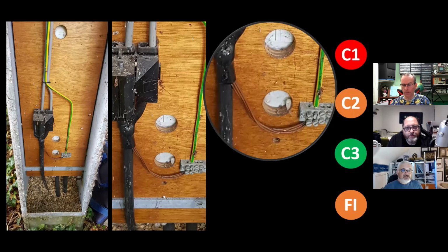Basically, what they've done is they've taken the armouring there, separated it, bent it down, and put it into an earth terminal. What they should have done is put the earth connection directly into that neutral there. That would have been a lot easier to identify then, wouldn't it? Yes, this is the problem. The configuration is in the eye and the competence of the jointer or the person putting in the cutout, and they're all different. And this is one of the problems, really.